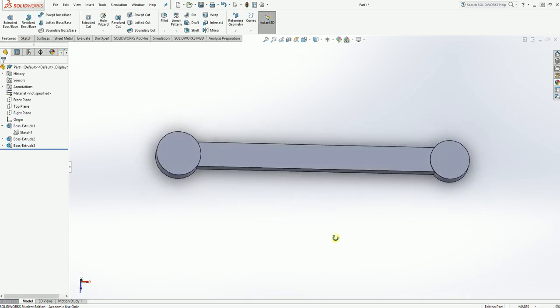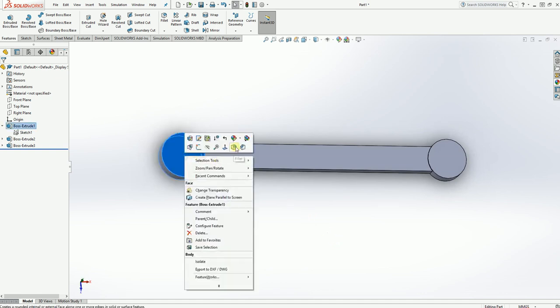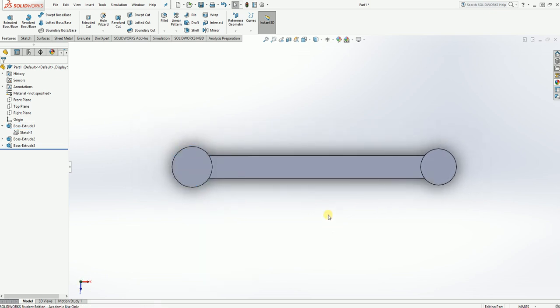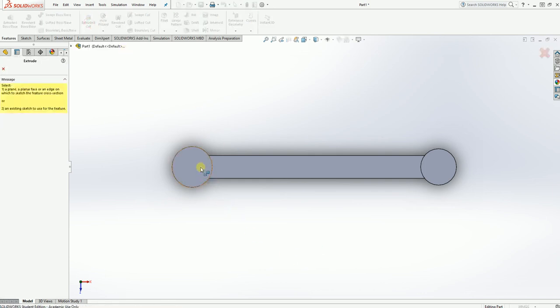Next I think we're going to do the hexagons, so the actual openings for the spanner, make it actually work. So I'm just going to spin round to normal 2. So now we're going to extrude cut these bits out. So it's very complex holes, so we're going to start with extrude cut. I'm going to select this face first because I want it to be here.